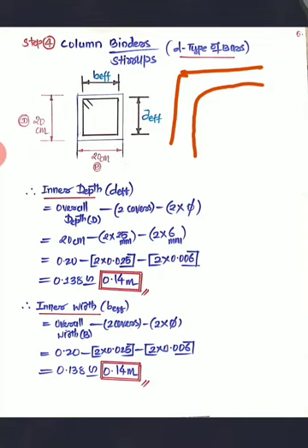So it is not going to be a sharp edge. If you were bending the bar at a sharp edge, then there would be no need to deduct this. But no one can bend in that way. Whenever you bend the bar, you will get a smoother bend there. So you will be deducting that here.